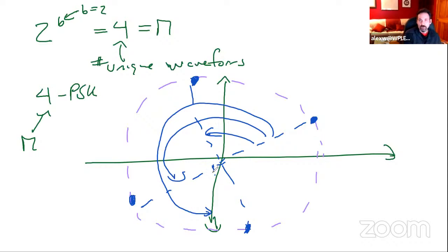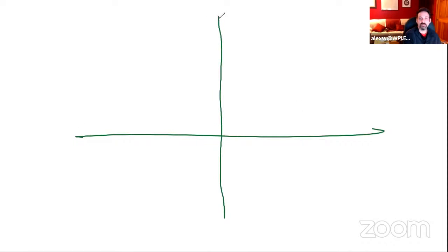Now, this is all great, but let's say we want to engineer something a little bit more robust, with phase values as distinct from one another as possible such that there's no confusion at the receiver. So often what we do is we choose phase values in that IQ plane, the in-phase and quadrature representation, such that the phase difference between any two is as large as possible to minimize any confusion, right? Because if we go back to this guy, let me illustrate.